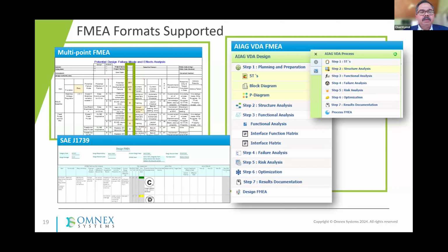It's just a fact. So, as we were doing functional safety, you probably heard me say I do audits. So I got quite involved. I'm an ASPICE principal assessor. I also do functional safety audits. And I came back and asked our FMEA gurus, why are the FMEA and the DFMEA and the HARA all saying different things? And the bottom line was, with electronic products, you have more than single point faults. Our fourth edition FMEA and the AIAG-VDA FMEA right now only handle single point faults or one single cause, whereas with electronics, about 20 to 30% of the failures are multi-point. And so sure enough, we designed the first multi-point FMEA.